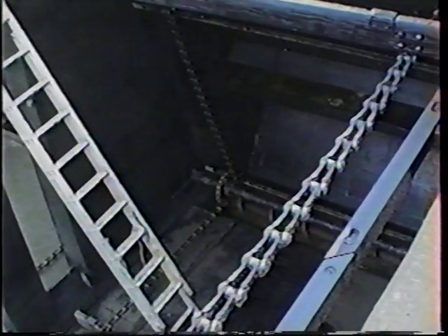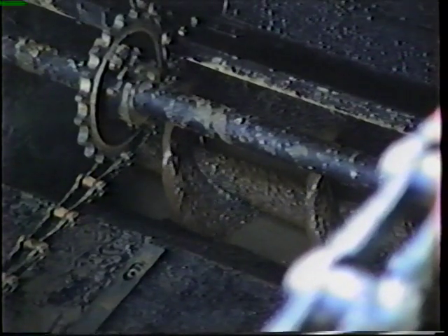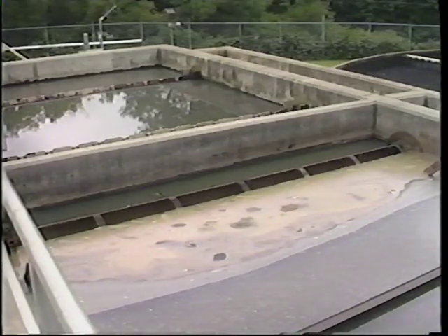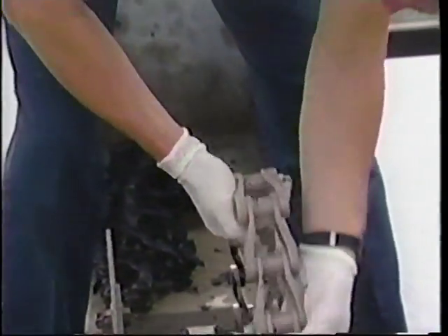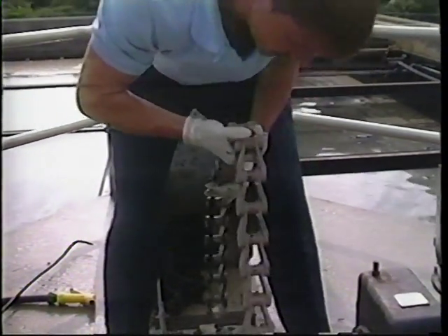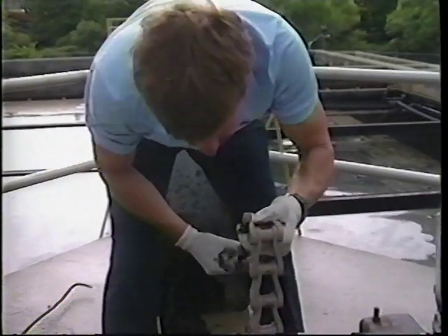The collection mechanism is a continuous chain and scraper assembly that travels slowly while scraping the settled biosolids into a hopper on the bottom of the clarifier. The mechanism then travels to the surface where it collects and moves the floatable solids to the scum removal device. In most cases today, the chain on the collection mechanism is made of a strong plastic material, and the flights or scrapers are made of fiberglass. Even the sprockets being used today are non-metallic. In older clarifier units, you may even find metallic chains with redwood flights.